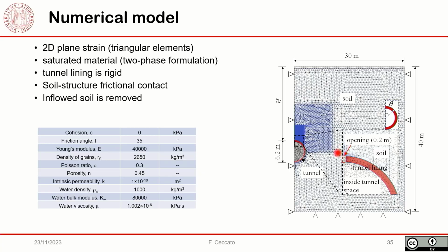But nowadays, in this code, in order to have an accurate estimation of the pressure around the tunnel, we need that this boundary doesn't move, or at least doesn't move too much. So since we wanted to calculate the reaction accurately, we had to keep the tunnel fixed. If we make it move, we will lose accuracy in the forces, but we get the displacement. So it's a matter of deciding what you want to get.